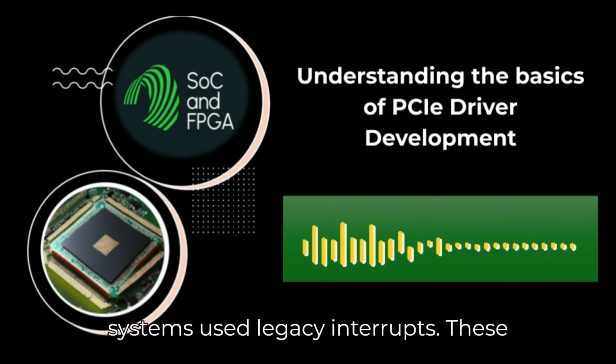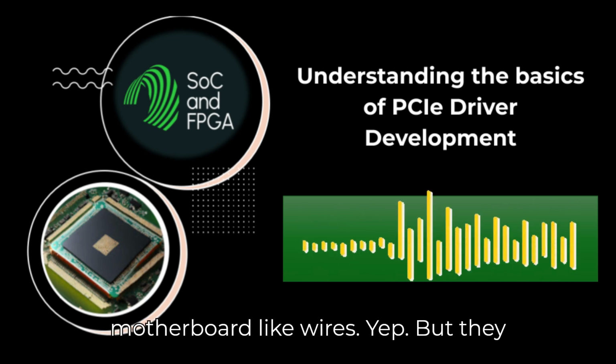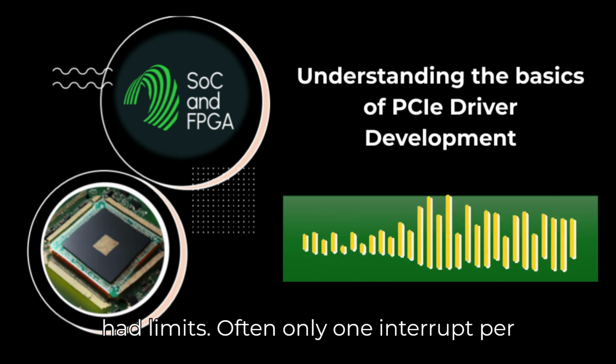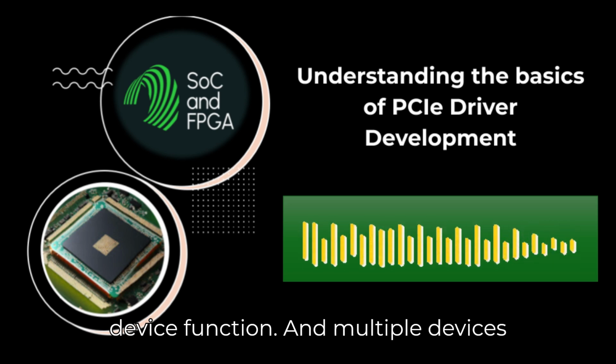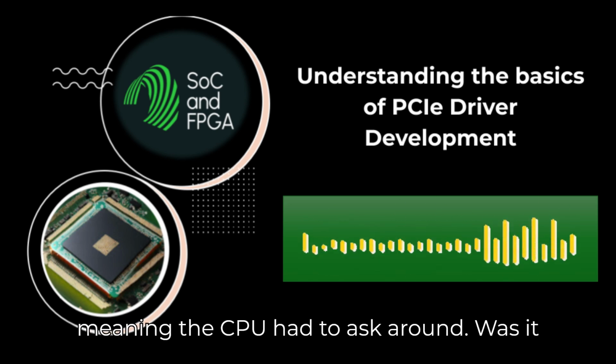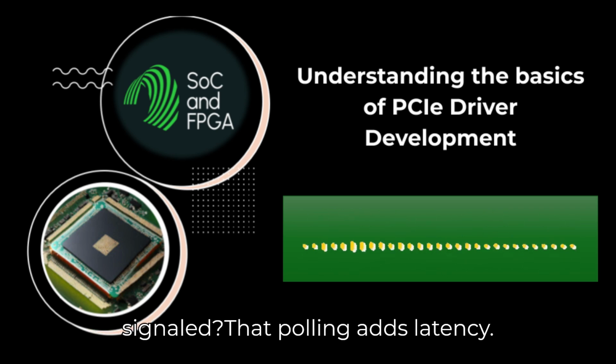Older systems used legacy interrupts. These used dedicated physical pins on the motherboard. Pins, like wires? Yep. But they had limits, often only one interrupt per device function. And multiple devices might share the same interrupt line, meaning the CPU had to ask around, was it you, to figure out who actually signaled. That polling adds latency. Sounds inefficient.